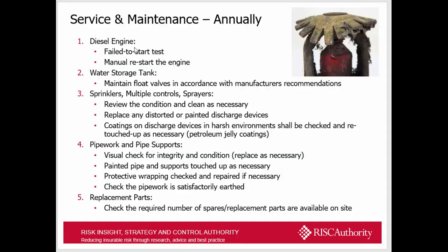Sprinklers, multiple controls and sprayers. So your nozzles as such, you need to review the condition and clean as necessary and replace any distorted or painted devices. And as can be seen in the photo top right there, this is a common issue that you'll see on a lot of sites where sprinkler systems have been in for many years. These sprinkler heads need to be cleaned, or this particular one, as you can see, the deflector plate is damaged, therefore that will need to be removed and replaced with a similar sprinkler of the same size.